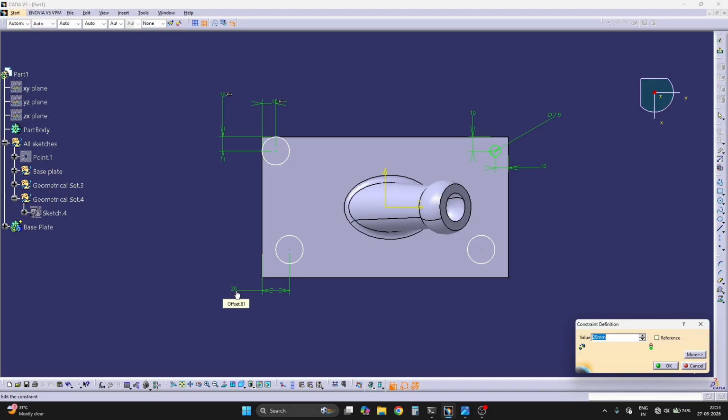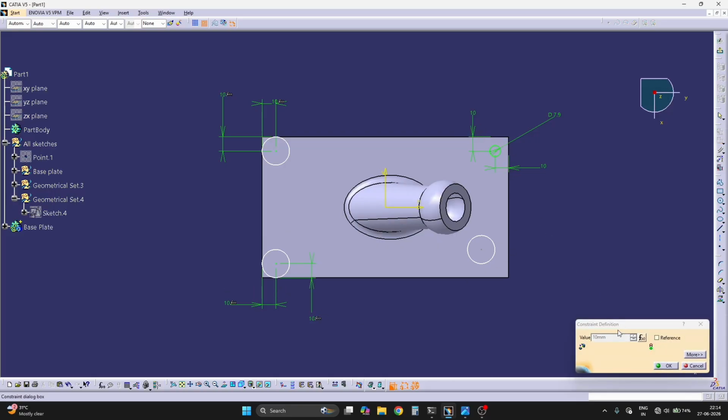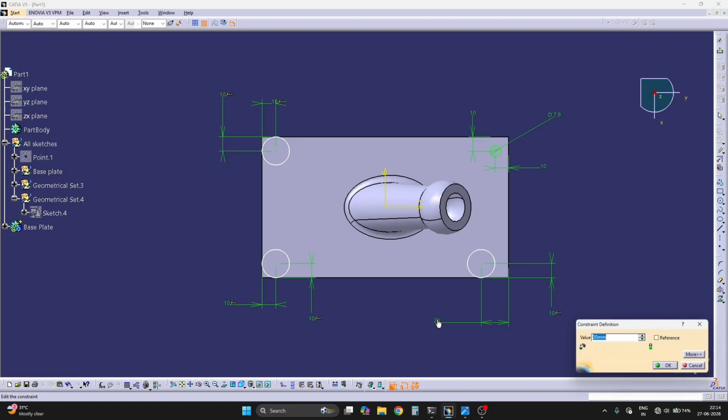Click on make is equals and select the one value, so that it will follow the parent dimension. Okay, make sure you're not tapping on that text. You have to tap on that. Okay, it is also working. Wherever you want you can touch it. Earlier one time it did not work like that. That's why I said it to you.